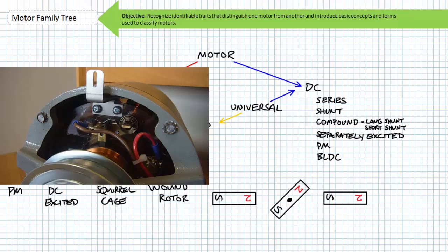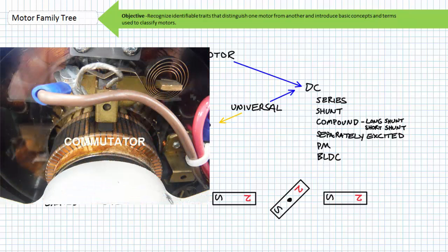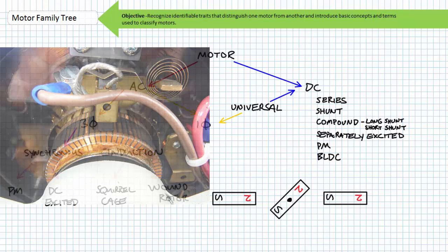Since the DC motor is powered by DC, the polarity of the applied voltage never changes. And the field winding, being a fixed winding, never changes physical position. Therefore, the resultant magnetic field produced by a winding subjected to this constant polarity voltage never changes. The field winding, being the fixed or stationary winding, never changes the location or direction of the magnetic field.